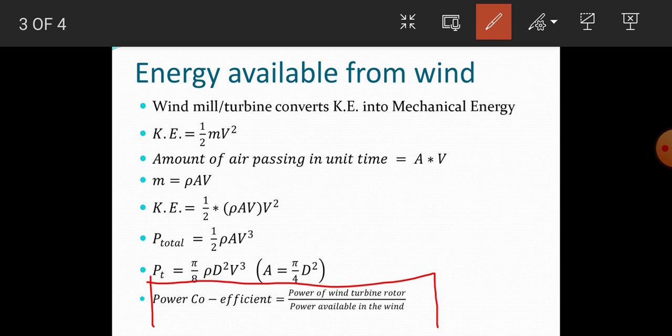An ideal rotor with propeller type blades of good aerodynamic design would have a power coefficient approaching 0.59, but such a rotor would not be strong enough to withstand the stresses to which it is subjected when rotating at a high rate in a high speed wind stream.